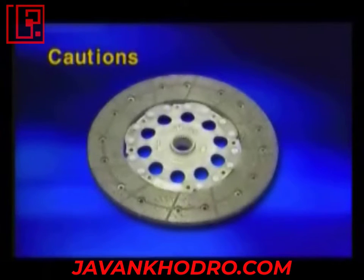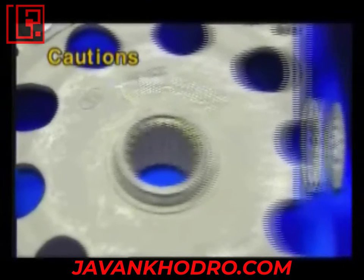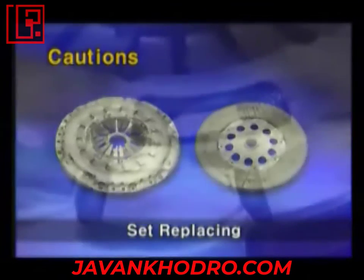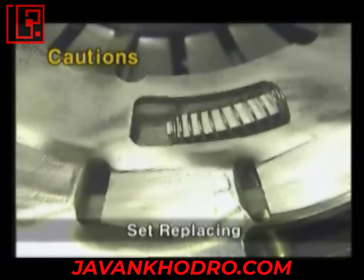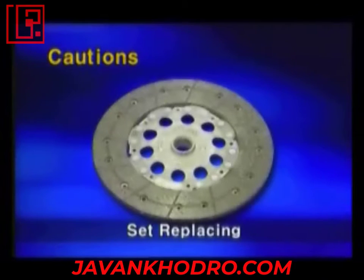Now, let's study the cautions at maintenance service. First, when installing the clutch, the TM side facing the clutch cover should be positioned. Second, when replacing the clutch, replace the clutch cover and clutch disc as a set. Because the clutch cover is adjusted with the worn amount of the clutch disc, if the worn clutch disc is replaced only, then disc slip can occur.